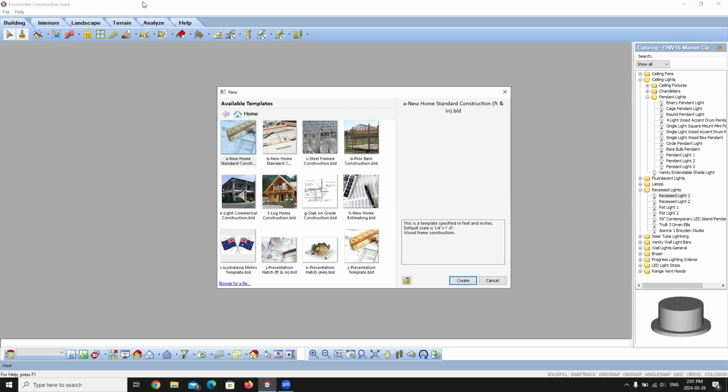Envisioneer offers many options for customizing your interface and the way that you draw. There are also settings that are specific to the current project and that will determine how your model will be built. Before drawing walls, you should select the precision you want for your measurements. You should set up your building location so that each element you insert is placed at the correct elevation within your model. There are also several drawing aids available that help to control your cursor behavior and the way in which the elements are inserted and drawn, such as your grid, your object snap, ortho, and collision.